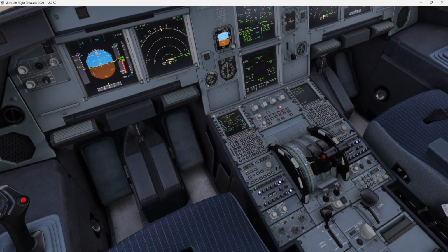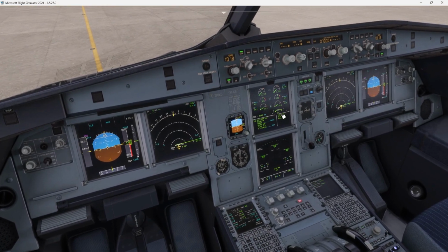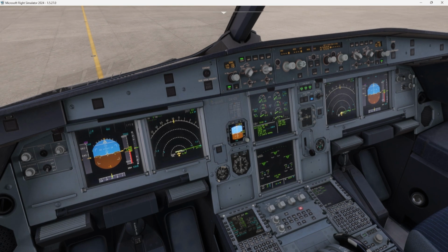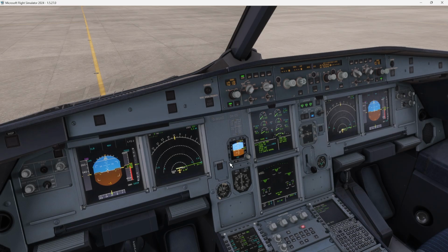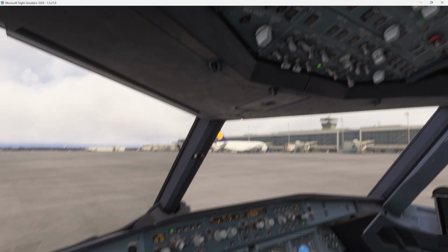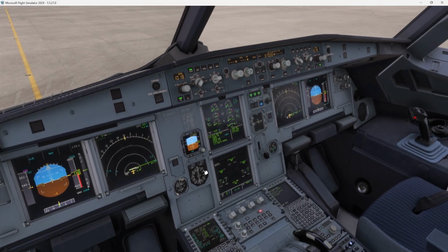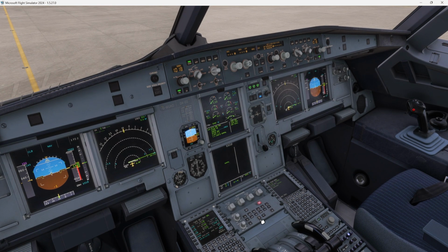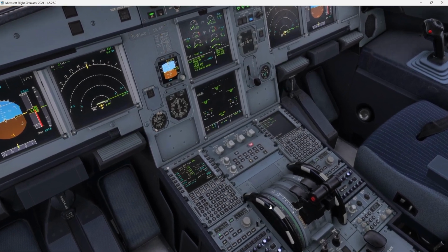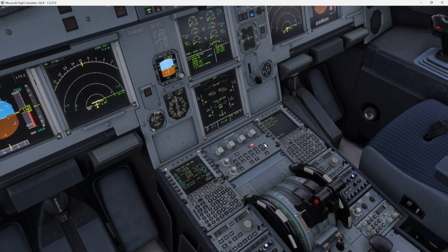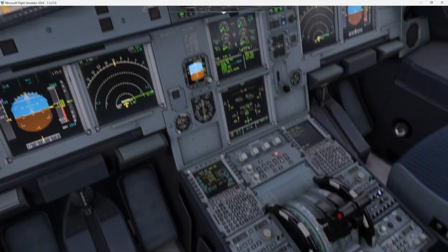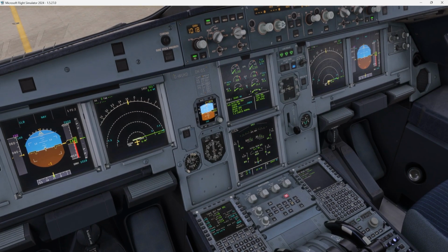Why? Because flaps are still in extension. Now it's okay. Yes. So let me bring the after startup checklist. Anti-ice not required, off. ECAM status normal. Pitch trim not yet. Now we do it down 0.5, so here one more, down 0.5. Rudder trim is neutral, and after startup checklist completed.